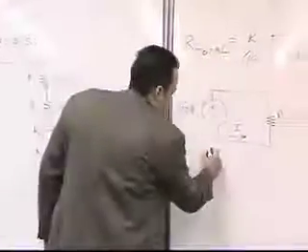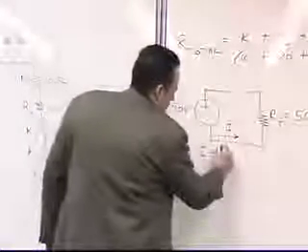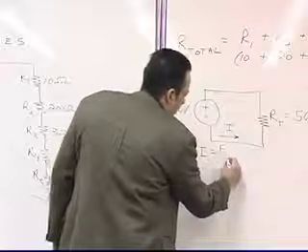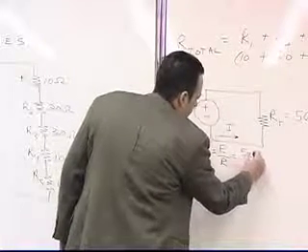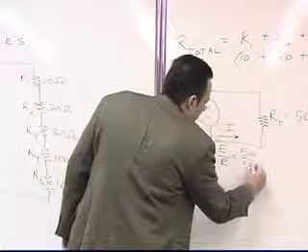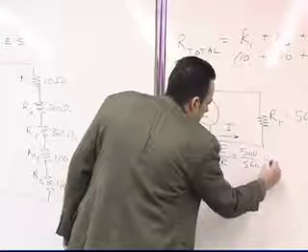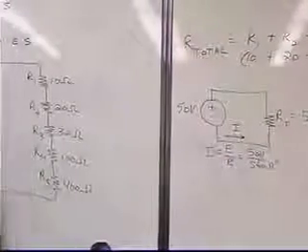Current in the Ohm's law wheel is equal to voltage divided by resistance. And in our case, that's 50 volts divided by 560 ohms. So what do you get when you pull your calculator out and plug those numbers in?